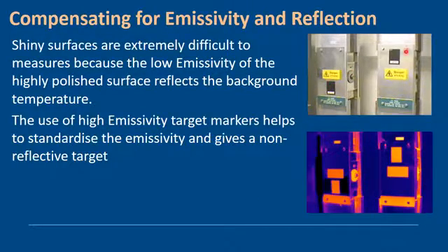Looking at this infrared image here, I can see that these tags are the IRISS IRD label systems where we actually write joint temperatures, etc. And you can see in the infrared image they're quite clear. But a point to note also, you see the danger 415 volt tapes, these plastic labels, all of these are non-reflective or minimally reflective with good emissivities. So even if you don't have ID labels, you can take temperature measurements off of these.